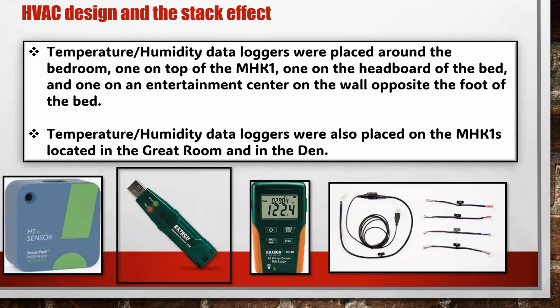But then we've got to contend with those expansion valves being at the indoor units and making noise. Those still don't really cover it. They're still too big for bedrooms, not even small bedrooms, average bedrooms. That's still a high load compared to what we see, 2000 CFM, 3000 BTUs in these rooms.